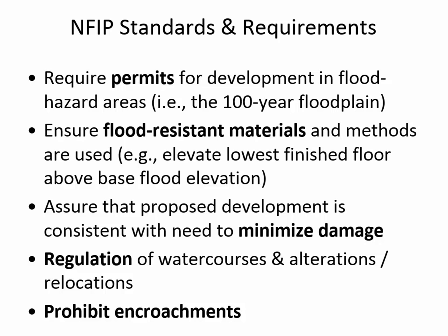The floodplain manager is supposed to look for ways to minimize damage, and so that might be elevating the structure, maybe putting in a garage on the ground floor and building above that ground floor, putting the inhabited areas higher, because that's usually where the most value of the structure is, people's furnishings and the expensive building materials are where the people are living. And then also a really important thing is that the floodplain manager is supposed to be prohibiting encroachments.